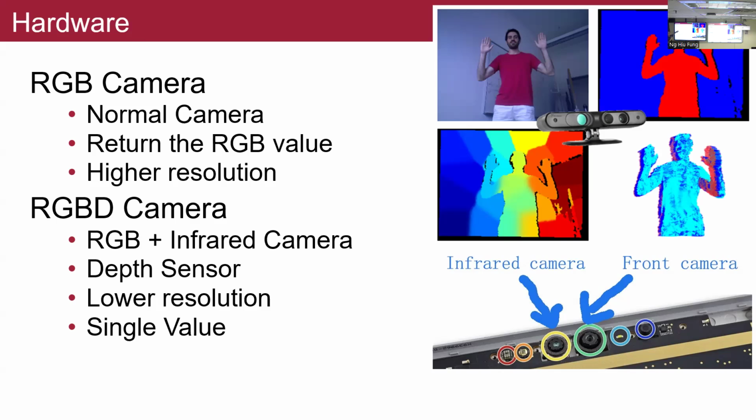Depth camera. Mostly, if you buy a home-use model, for example the Microsoft Azure Kinect, there are three depth cameras, and each of them is around 600-something by 400-something pixels. That cannot compare with RGB quality. Yes, a depth camera also has pixels. Compared with the resolution, the cost, and the power consumption, the depth camera is not so good. But somehow it can scan the 3D structure.